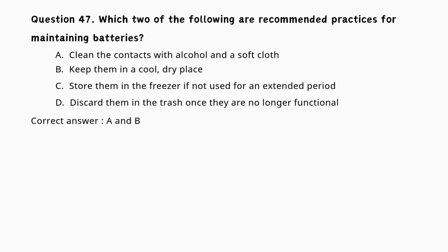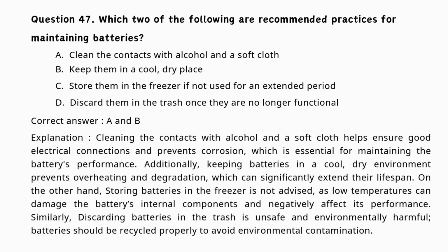Correct answer A and B. Cleaning the contacts with alcohol and a soft cloth helps ensure good electrical connections and prevents corrosion, which is essential for maintaining the battery's performance. Additionally, keeping batteries in a cool, dry environment prevents overheating and degradation, which can significantly extend their lifespan.